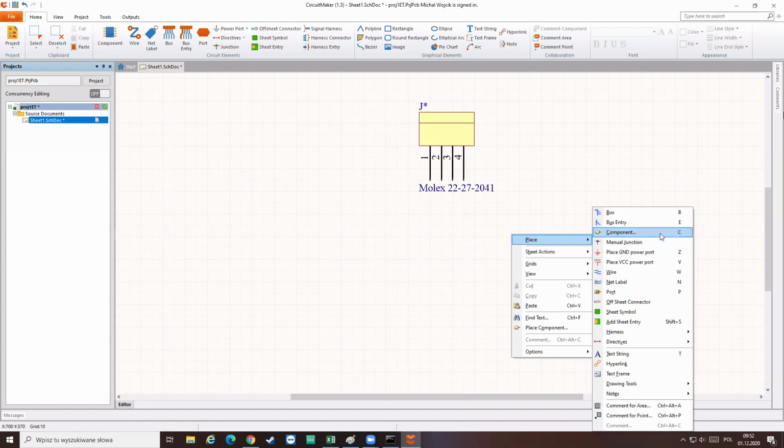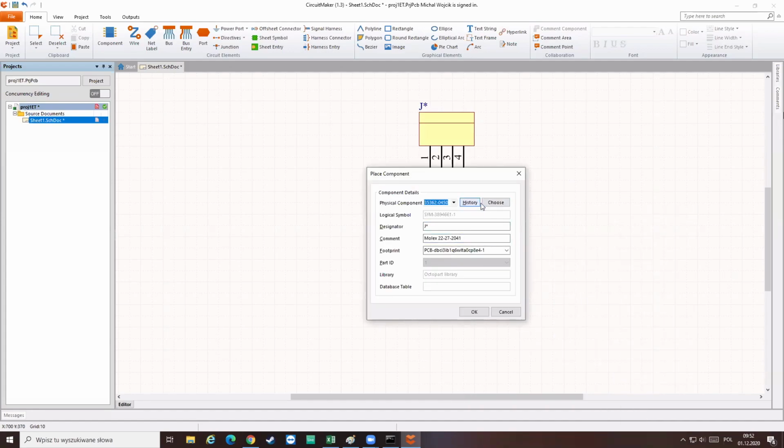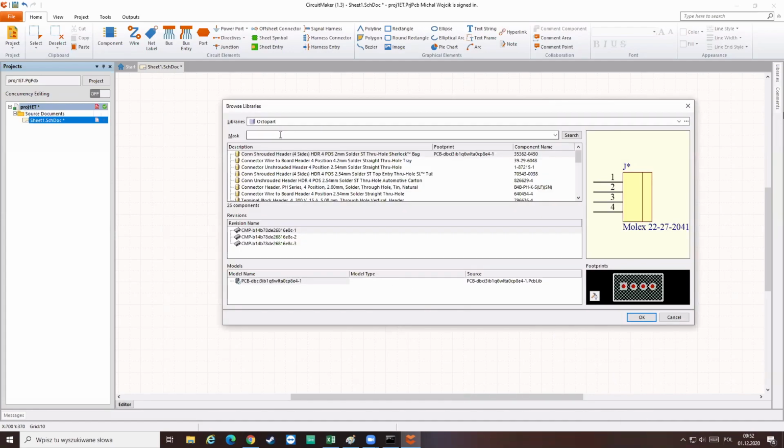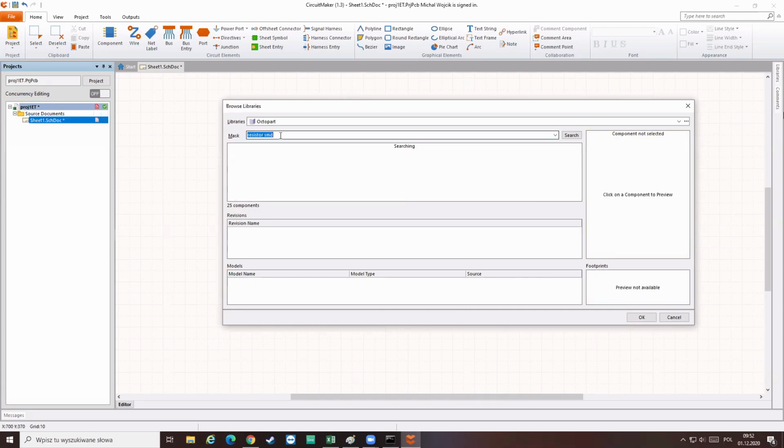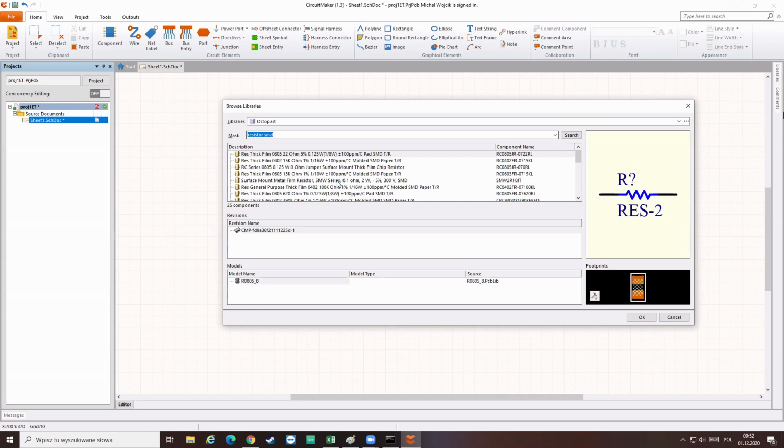Okay, let's add a new component. I wish to find just some resistors maybe right now. Let them be SMD, so resistor, SMD. Okay, already searched for that. And I'm selecting, let's say, package 0805 resistor. We'll talk more about the details in the next classes. Today, I just want you to make just a fresh start to PCB making. Resistor with some R0805 footprint. This is fine for me.